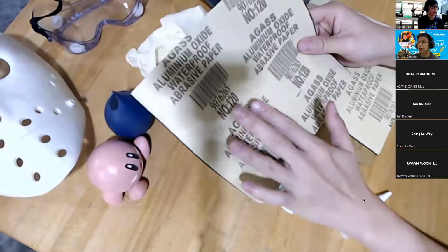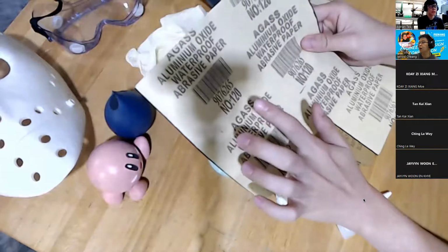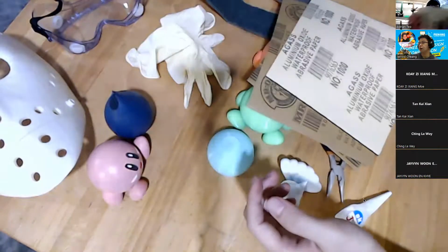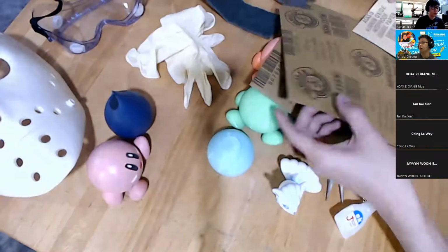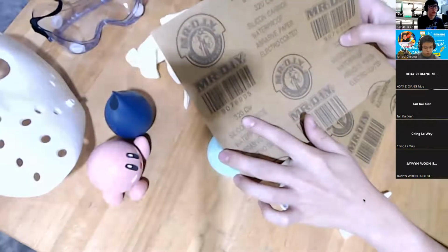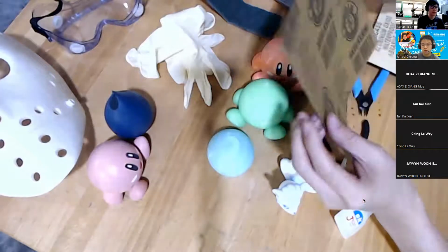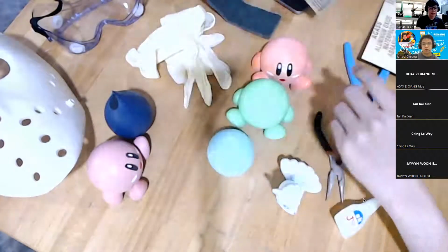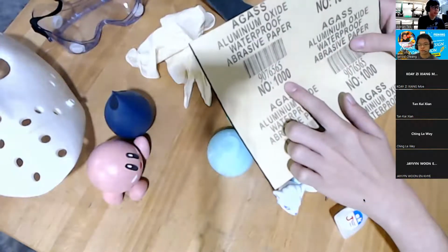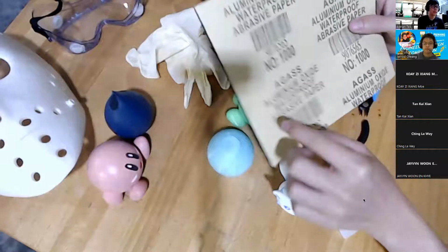So when you sand your 3D printed parts, you start by sanding with the lowest number you have. You can start with 80 or you can start with 120, and then you start sanding your parts. Later I'll show you how. And then after that, you move on to a next bigger number. I have it over here, 320. But of course, you can use 220 if you have it. And then you move on to 600. And then lastly, you move to 1000. Make sure when you buy your sandpaper, it has to be waterproof so that you can dab some water on your print and you can sand it with water.